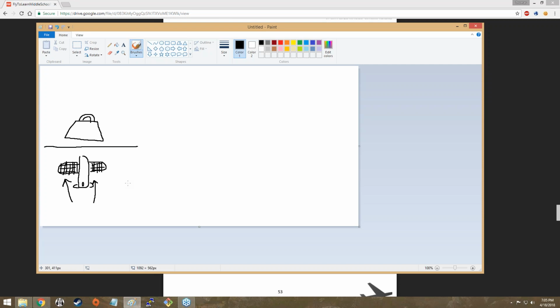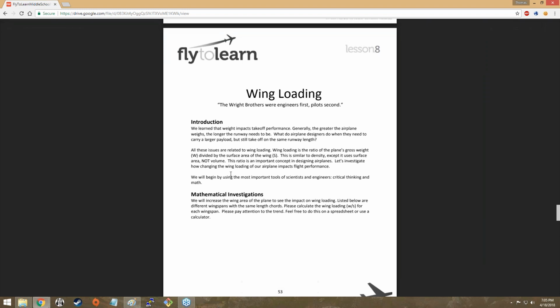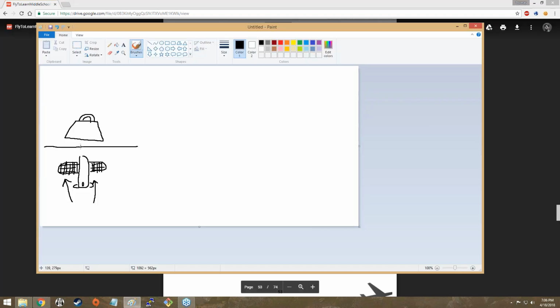So basically, the way you determine wing loading is you divide the plane's gross weight, so how much it weighs, by the length times the width of the wings, or wingspan times mean chord. And this gives you a ratio. And the whole idea with this ratio is there is no one particular area on the wing that is meant to do all of the heavy lifting, right?